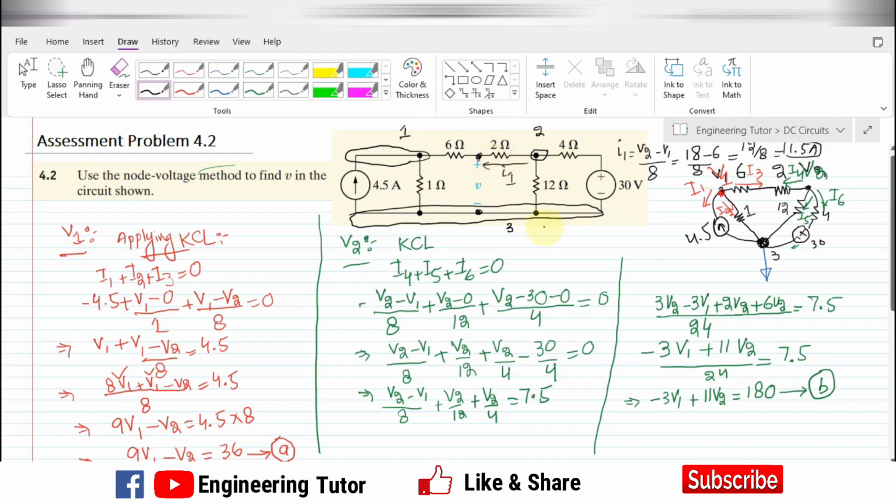Similarly, the voltage drop at this 2 ohm resistor, this is plus, this is minus, let me call it V0. So the value V0 here is equal to 2 multiplied by I1. So 2 multiplied by 1.5 is equal to 3 volts.